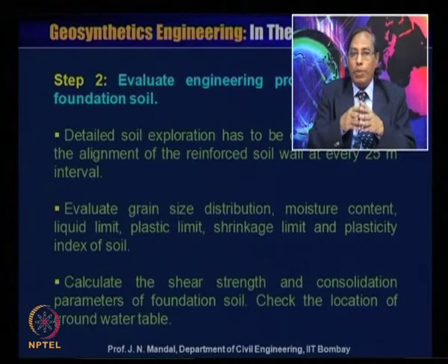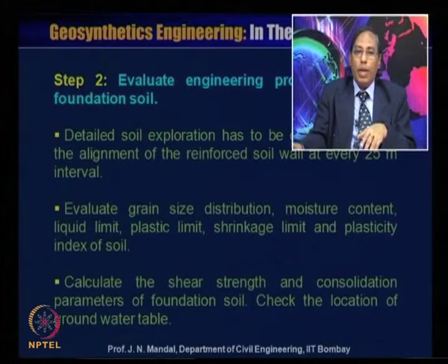And you have to evaluate what will be the grain size distribution curve, what will be the moisture content, what is liquid limit, plastic limit, shrinkage limit, and plasticity index of the soil. And you calculate the shear strength and the consolidation parameter of foundation soil and check the location of the groundwater table. So these are very common that what has to go for the soil testing.